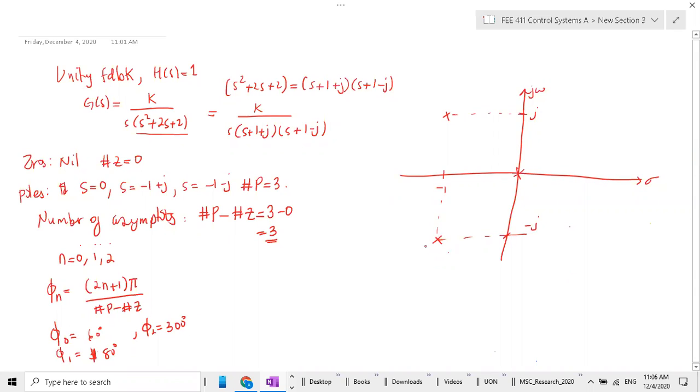So next you look at the real axis and locate the root locus. If you stand here, there are no poles and zeros in that direction, so this is not part of the root locus. If you stand here, there is only one pole in that direction. So the whole of that line is part of the root locus. So this one will go and look for a zero. Remaining are these two.